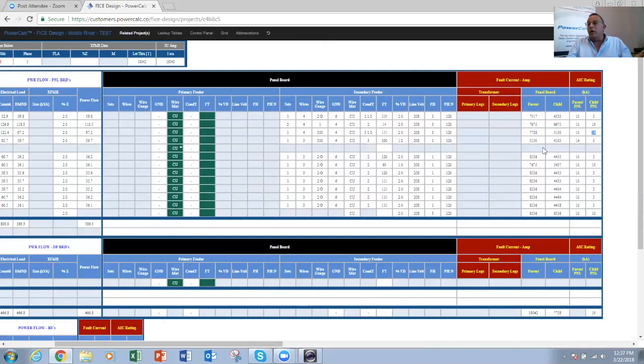These are basically Ohm's law, that I equals V divided by R. Based on Ohm's law, the values that affect the amps are going to be the impedance and the voltage. Of course, related to the impedance will be the distance that the fault current is going to travel. The longer the conductor, the more energy is going to be dissipated through that conductor, and thus the fault current at the end of the conductor would be less the longer it is.